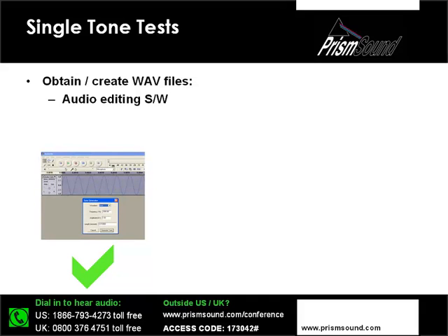One thing you do need to be concerned with is whether or not your editing software is accurately creating the amplitudes, the frequencies, and in particular the dither when it truncates the signal to a fixed word length. That's something that is taken care of in professional audio systems like the Prism Sound Sadie software, but you do need to be careful because it's a little bit difficult to verify whether your editing software is doing exactly what it claims to be doing.